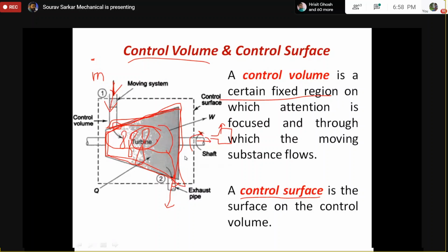So a control volume system is basically different from the control mass or the closed system. In the closed system there is no mass transfer, but here there can be heat transfer. So during this process, you can supply some amount of heat, and you can extract some amount of work. Whatever you like to do, you can do. And also the mass can enter into the system and the mass can leave the system. So this kind of system is basically called a control volume system, and this process is basically called a flow process, because the process is happening during the flow.